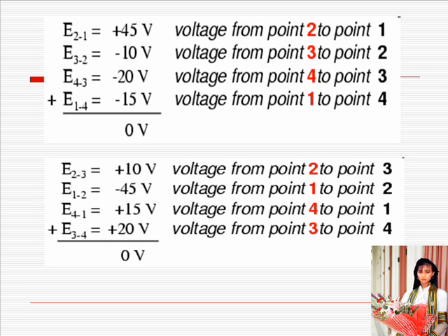By algebraic, I mean accounting for signs, polarities, as well as magnitudes. By loop, I mean any path traced from one point in a circuit around to other points in that circuit, and finally back to the initial point. In the above example, the loop was formed by following points in this order: 1, 2, 3, 4, 1. It doesn't matter which point we start at or which direction we proceed in tracing the loop. The voltage sum will still equal zero.